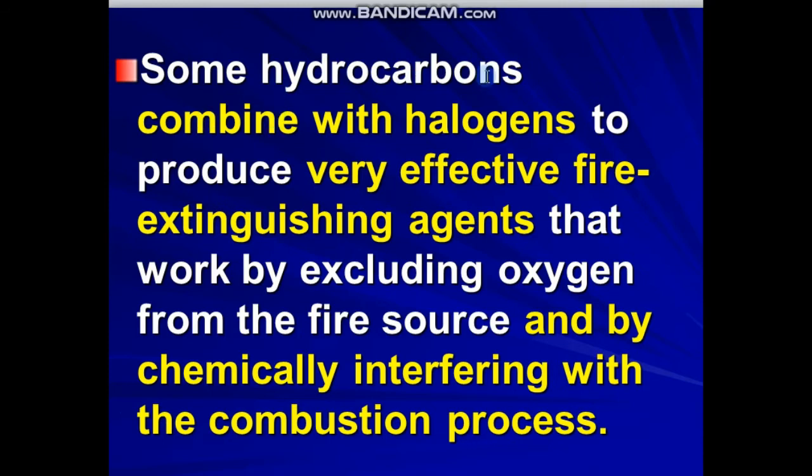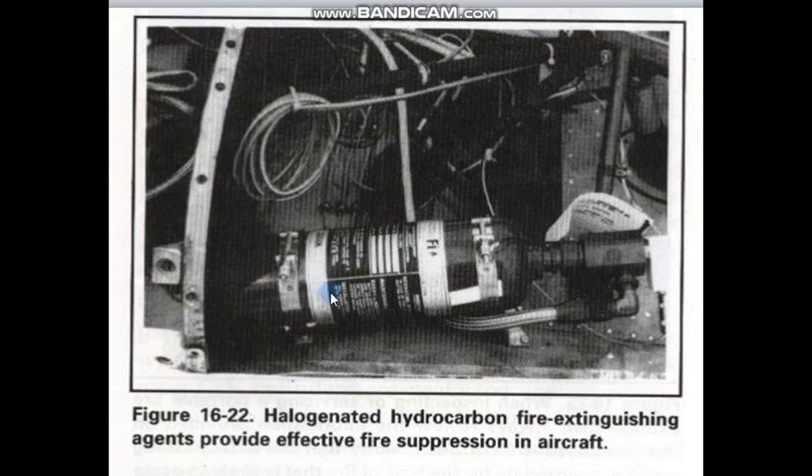Some hydrocarbons combine with the halogens that we talked about before to produce very effective extinguishing agents that work by excluding oxygen from the fire source and by chemically interfering with combustion processes. In this figure, we see a halogenated hydrocarbon fire extinguisher cylinder.